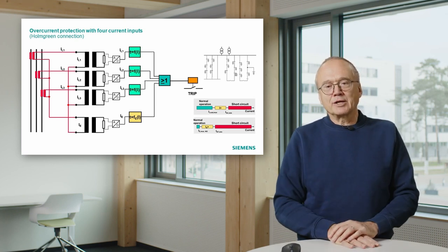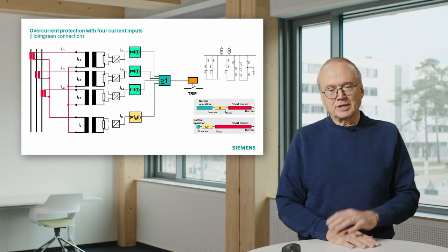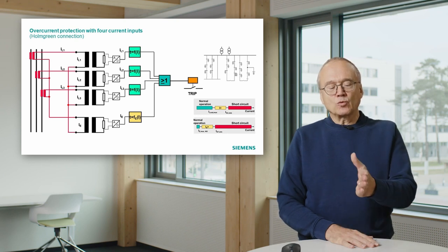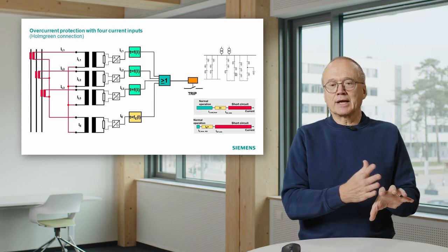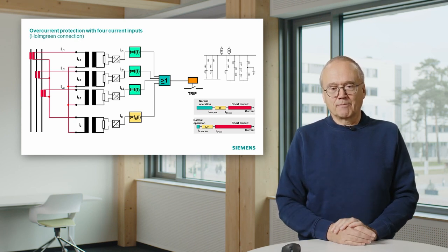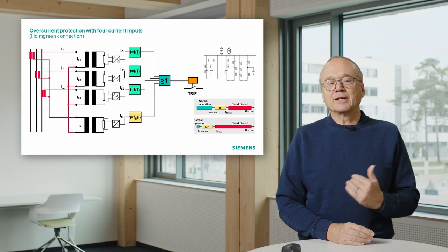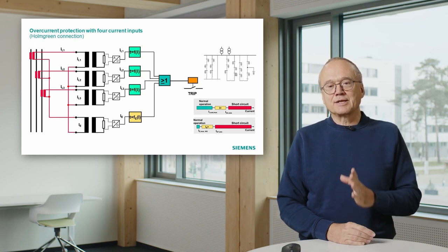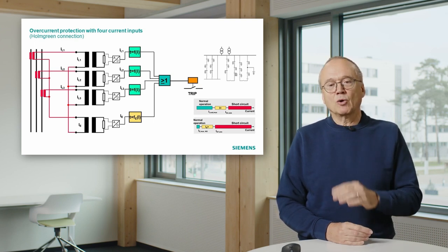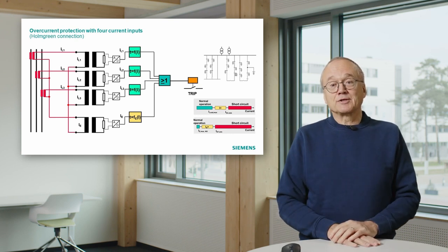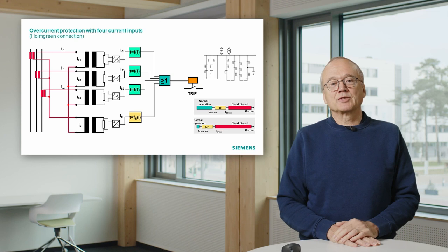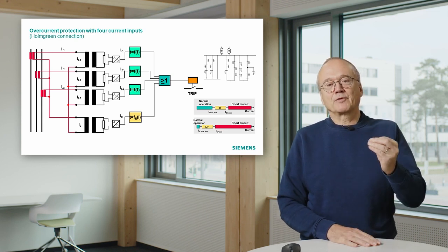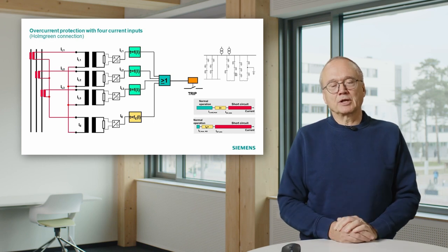And then we have the range of short circuit currents, which is indicated in red color here, and we normally have a setting value somewhere between the red and the green area. Selectivity is first of all about how to define this value, and the second parameter we can influence is we can think about time delays. That means if we are above that limit, what is a proper time delay?